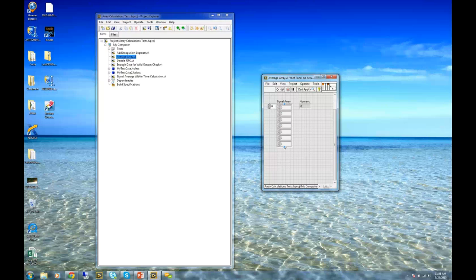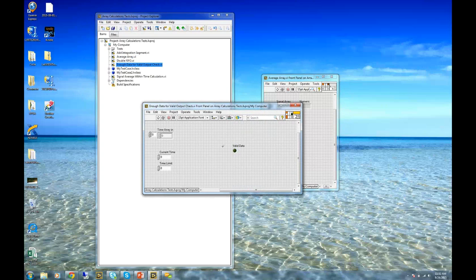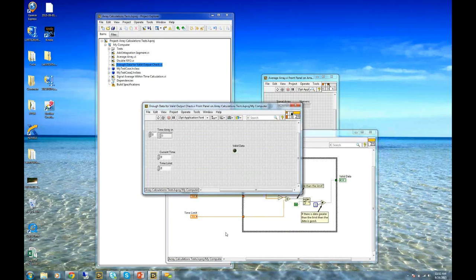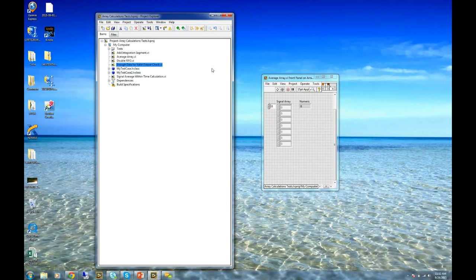Now what I actually do is I have an array of timestamps where I say I need to get so many pieces of data out and take the average. There's a varying amount of data from this array that I need to take and create an average and drive a PID closed loop control algorithm.